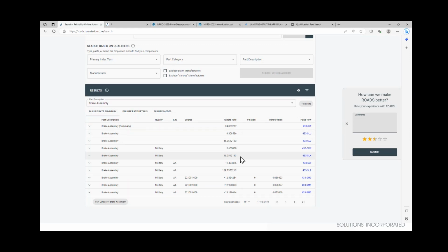If you look up that same electrical connector in NPRD, or sorry, in EPRD, you will see failures per million hours. If you look it up in NPRD and you look under ground mobile, you may find that the electrical connector is used in a car or a vehicle and the failure rate will be presented in miles. Thank you for bearing with my little bit of confusion there.